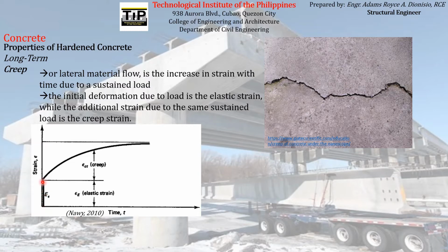Actually, in a certain period of time only. But after some time, you can see here that there is an additional strain being experienced by the material. After it experienced the elastic strain, after some time, the strain being experienced by the material increases. And that additional strain being experienced by the material as time goes by, as it supports a sustained load, is what we call creep.